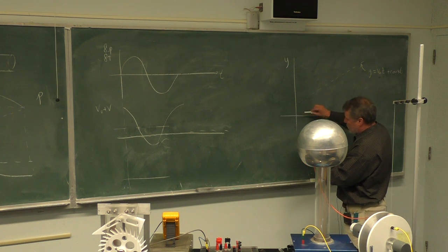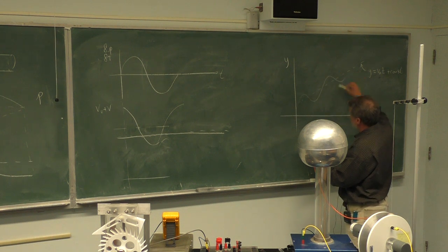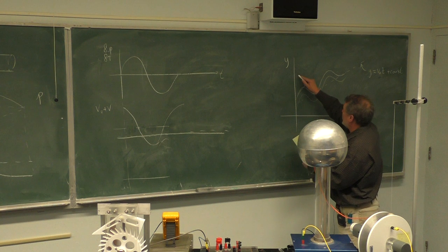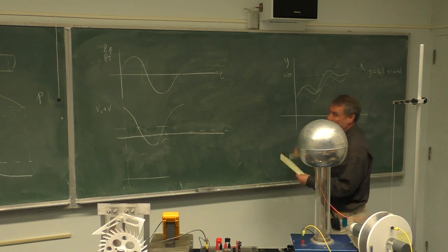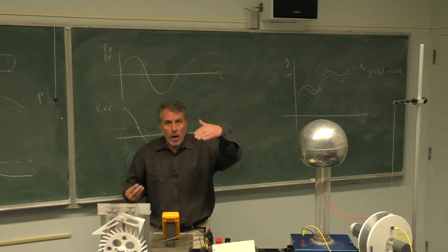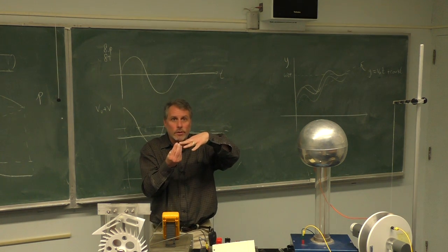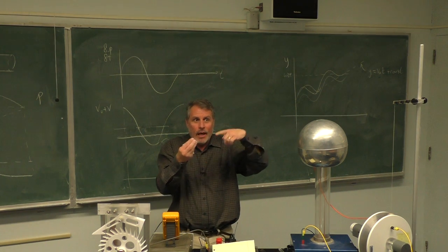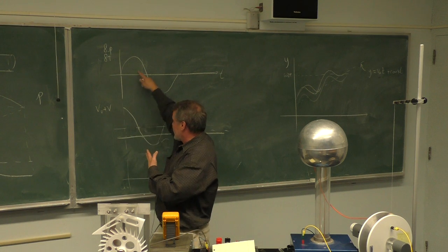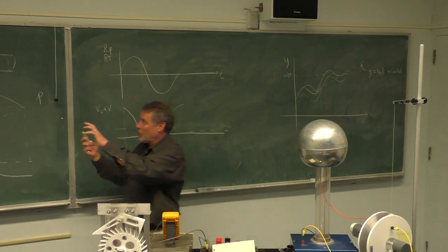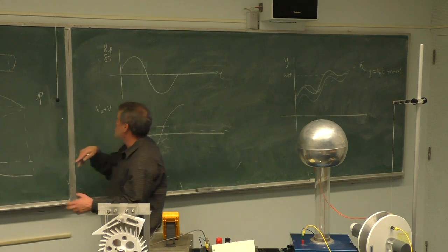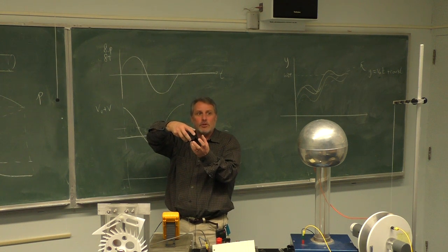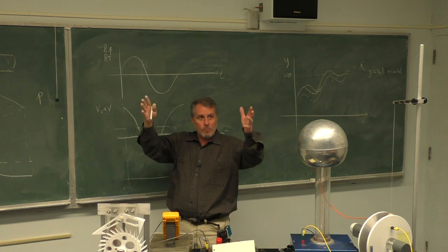So a fluid particle is going to be undergoing excursions like so. One that is higher up is going to be undergoing the same periodicity, but is now going like that. And now imagine that at some point you have the wire. That's where the wire mesh is. So a fluid particle comes from a region that is, say, room temperature, goes through the gauze, the metallic mesh, and then gets a temperature increase. And if you are in the right place of the pipe, as I drawn, the pressure would be this if the velocity is like that. When the gauze is a quarter of the distance, say, then I'm going to bring a fluid particle that has an excess amount of temperature at the time where the sound is compressing.